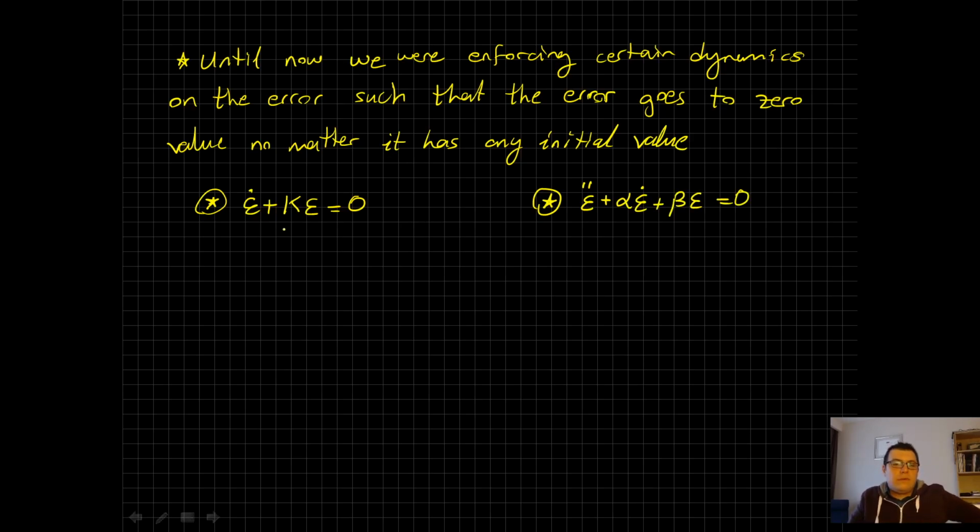So that was for example, velocity control and generalized error control, or for force control, assuming that you have the environment with losses, so environment with damping. That was also used for pure position control when the error is defined only in terms of the positions, and for force control when you had the environment being assumed as pure spring.